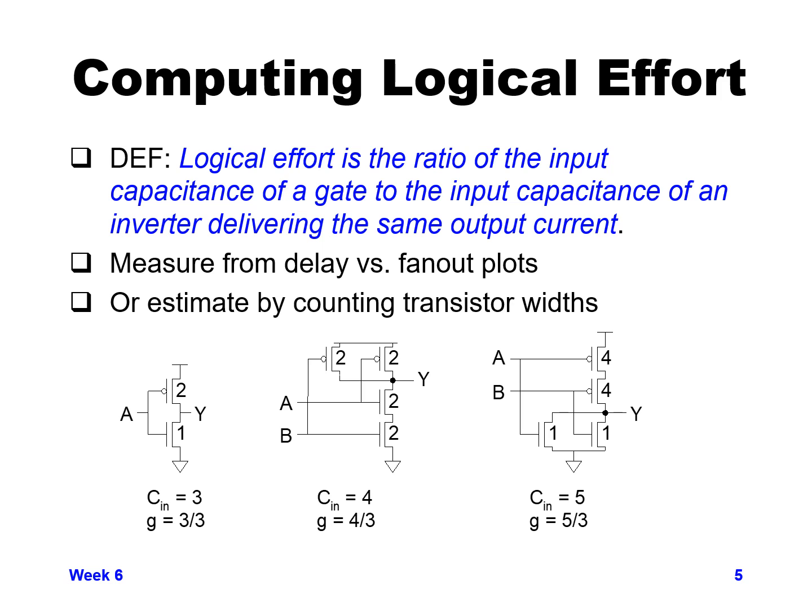Now if we look at a 2-input NAND gate, which is the center of the 3 circuits below, we can see the NMOS devices. We have 2 NMOS in series with each other. Since we want to deliver the same amount of output current as the basic inverter, 2 NMOS in series, if they were both size 1, would have half the amount of output current. It's like placing two resistors in series with each other, so it's going to have twice the resistance. So in order to have the equivalent resistance of an inverter, a NAND gate has to have the NMOS devices be twice as wide, so that when you put two of them in series with each other, it has the same equivalent resistance as the inverter.